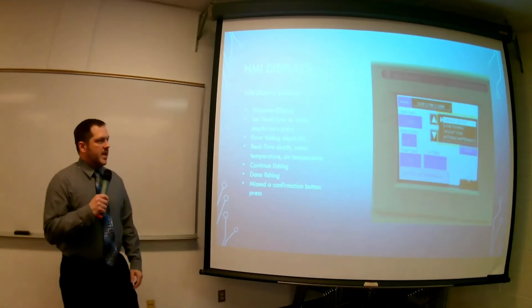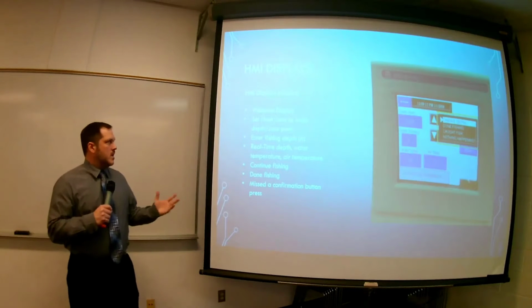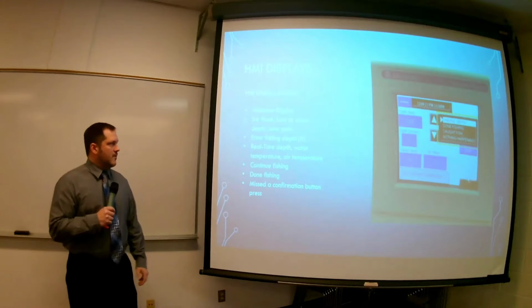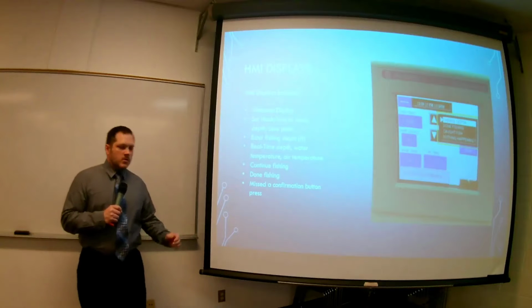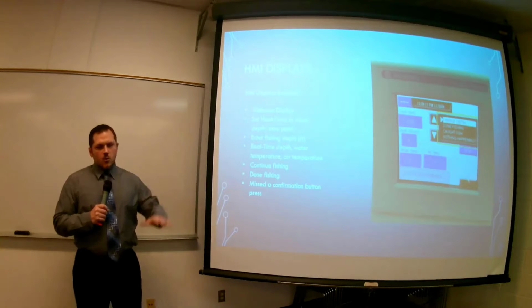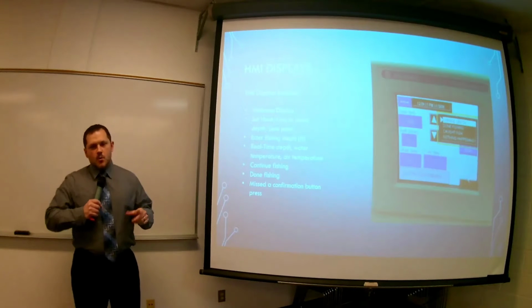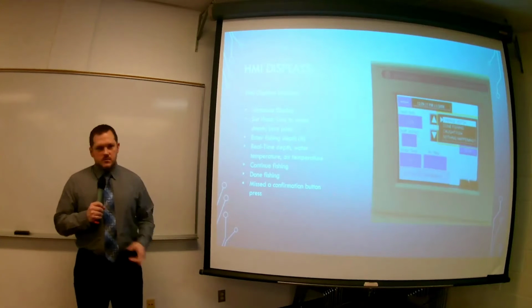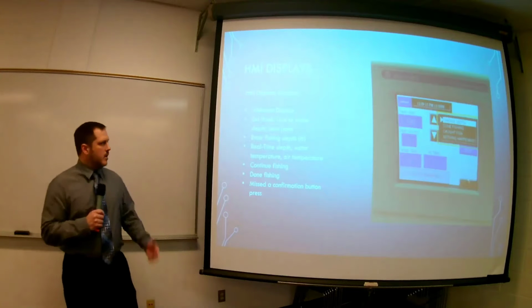Hi. Yeah, so some of our page displays that we have: just the welcome display, the display that pops up right when we power on. We have our set hook and lure to water level. So what that's really doing is when we go to the water level and you hit the confirm button, that's going to be important later, but that's when we actually start sensing the Hall effect sensors. So we're actually tracking actual depth then.